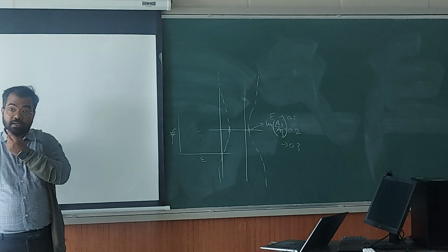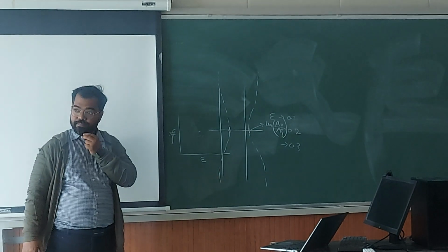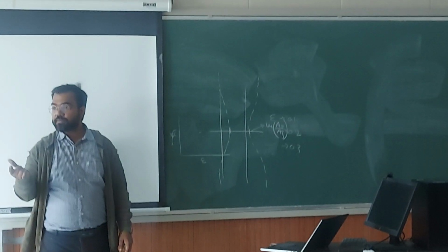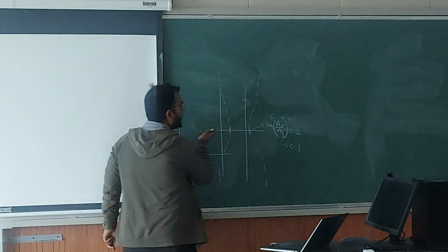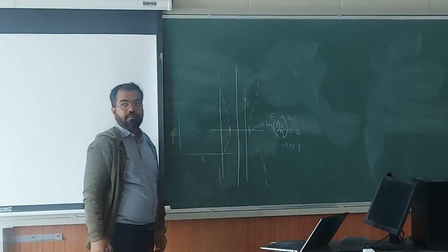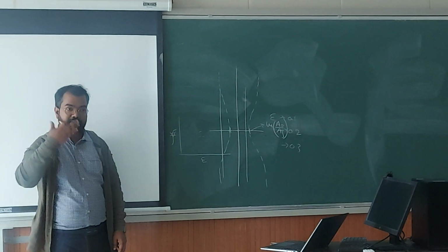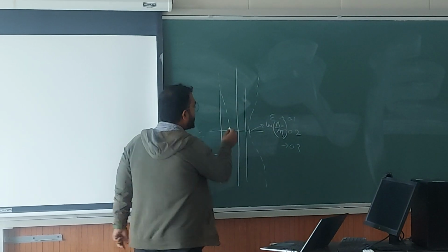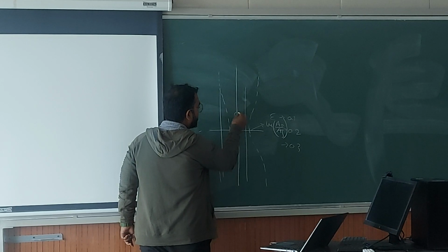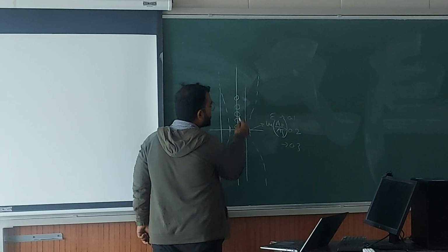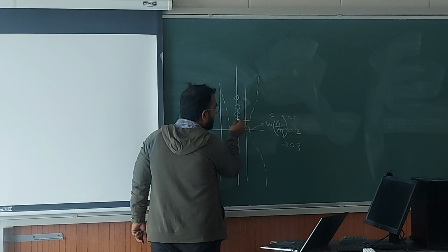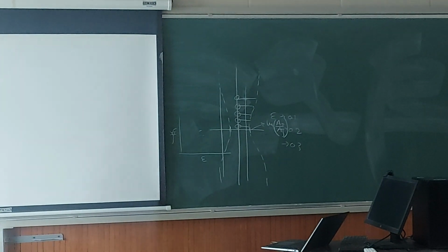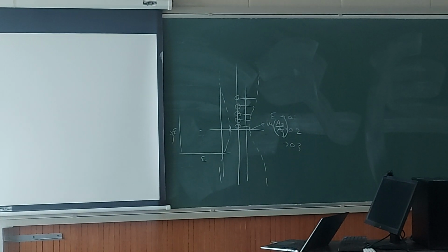Instead of doing 10, 20 specimens, you can also do it in one specimen. Okay? So you stop it just before failure or as soon as the necking develops. And then instead of cutting like this, you cut it like this along the axis, and look under the scanning electron microscope, and you will find different amounts of void volume fraction here, here, here, and so on. And in one specimen you can also measure how much area reduction has happened at these points, and from one specimen you can calculate strain versus void volume fraction.